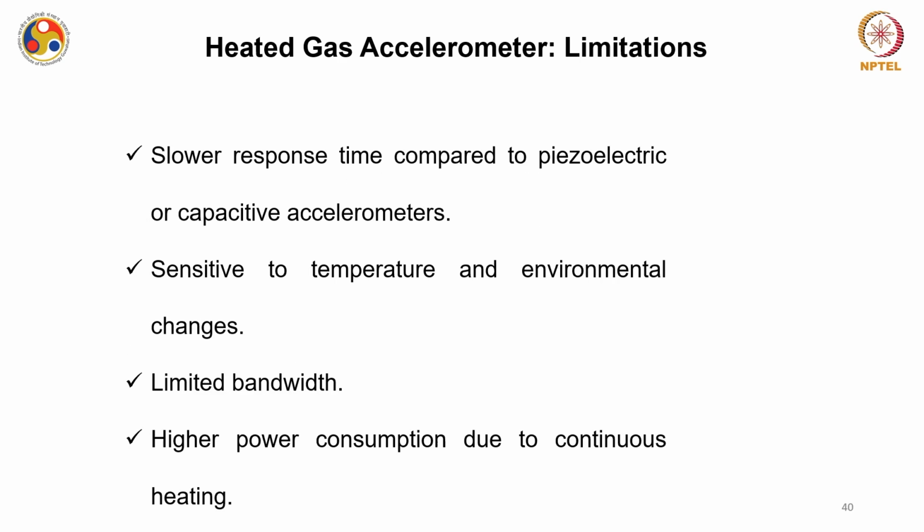Okay. However, there are several limitations also associated with HGA, like their response time is slow if you compare it with any piezoelectric or capacitive accelerometer, which makes it less practical. Okay. They are sensitive to temperature. We have just seen one curve for sensitivity versus ambient temperature. Okay. And their bandwidth is limited. Okay. However, for piezoelectric devices, the bandwidth is very high, or at least decent as compared to the HGA devices. Okay. Their power consumption is really high, because of the continuous heating of the heater.